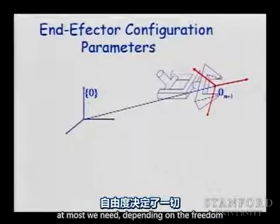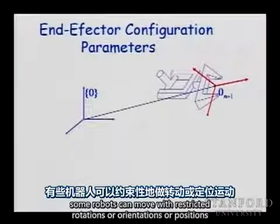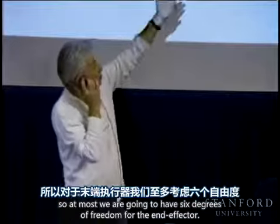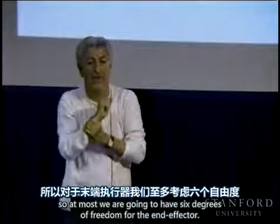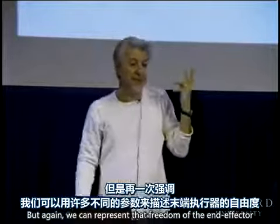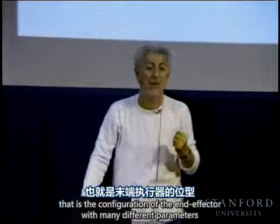So if we have just one end effector in the robot, essentially we have just one rigid body. At most we need, depending on the freedom, because some robots can only move in the plane, some robots can move with restricted rotations or orientations or positions. So at most we are going to have 6 degrees of freedom for the end effector. But again, we can represent that freedom of the end effector, that is the configuration of the end effector, with many